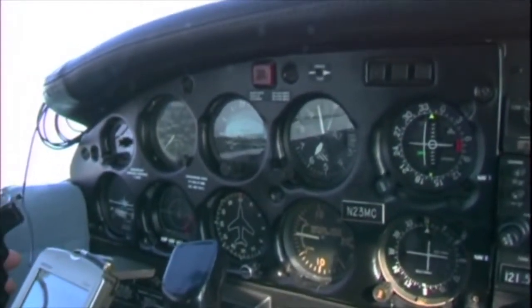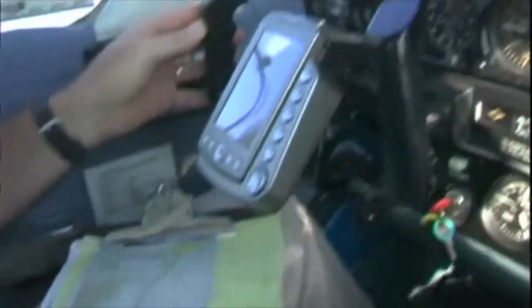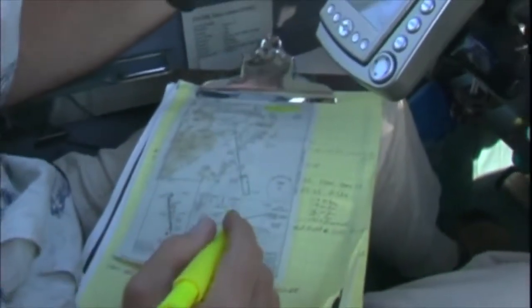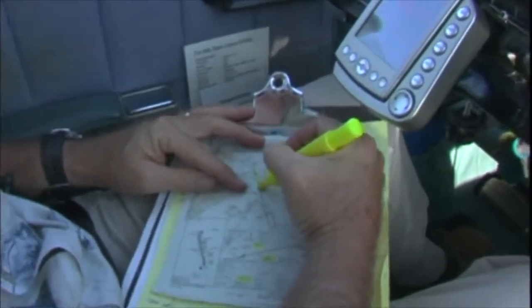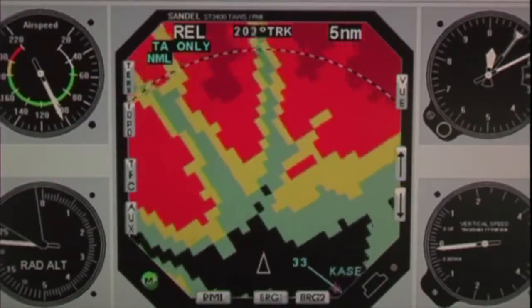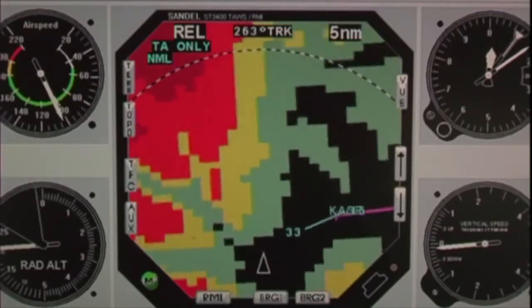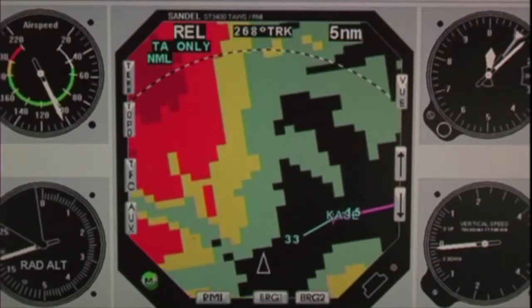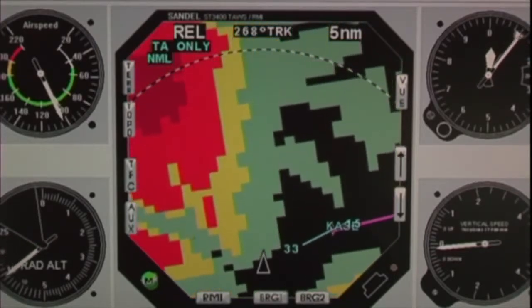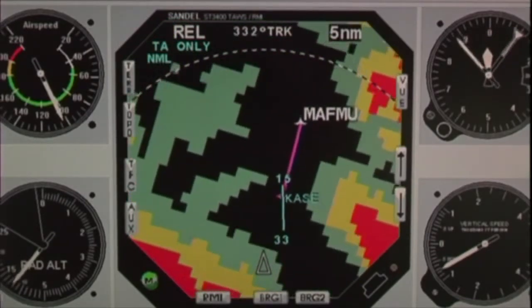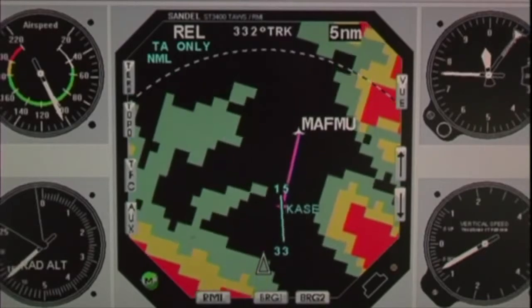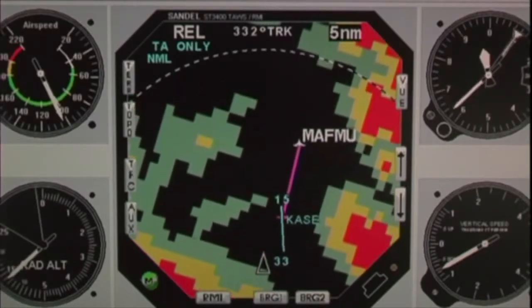Good aeronautical decision-making means you, the pilot, must study the charts before leaving cruise altitude, and proper execution of the approach or the missed approach is critical. If, for example, the course between the initial approach fix and missed approach point and the airport is not a straight line, executing a missed approach with a turn before the missed approach point could be hazardous to your health.